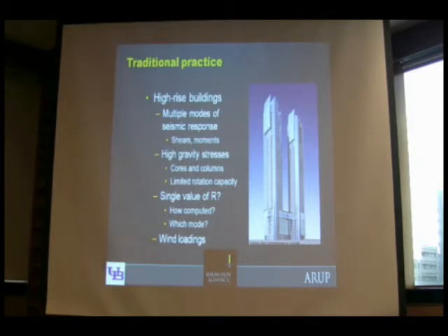If one was to use a traditional approach to designing high-rise buildings, namely compute base shear by analysis of your structure and the use of a response modification factor, what value of R do you use for these framing systems that are widely used in tall buildings? Is a single value of R appropriate? Should you use a different response reduction factor for modes 1 and modes 3? It's impossible to know unless you do a case-by-case analysis, in which case you can probably go ahead and perform a performance-based design. Also, for high-rise buildings, wind loadings can often control.